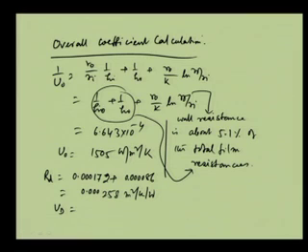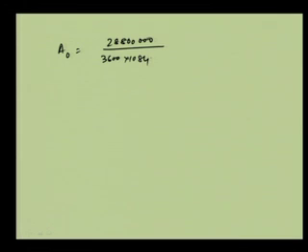And then UD you will get from the relationship of this, and UD we can find out as 1084 watt per meter square per Kelvin. Now, once I know UD, we can find out the area based on the outside diameter, which is 288000 by 3600 into UD into delta T LM.